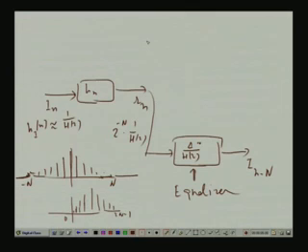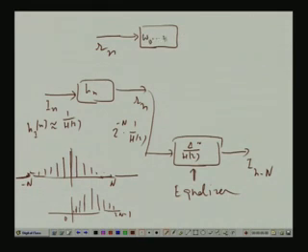There is a training phase during which the transmitter transmits some known sequence I n, which is also known to the receiver. The standard sequence is called pilot sequence. So, the receiver knows what the equalizer output should be ideally, that is what was transmitted. So, it takes the received signal R n and constructs an adaptive filter, because this equalizer is a causal FIR system of length 2N as I showed. So, you construct an equalizer W 0 to W 2N minus 1.